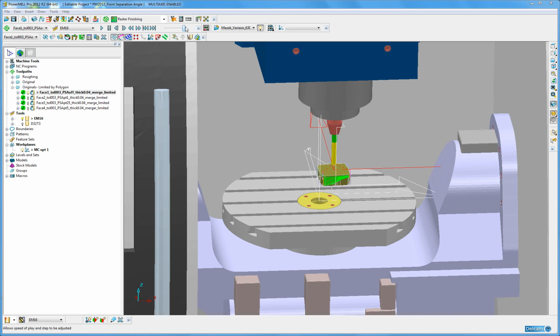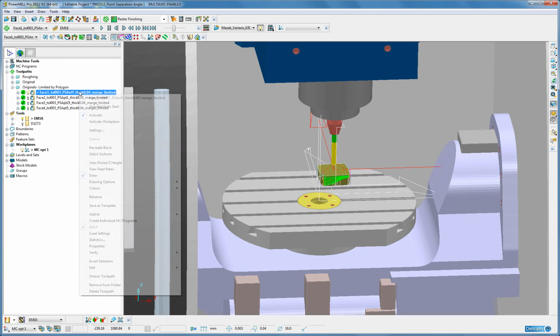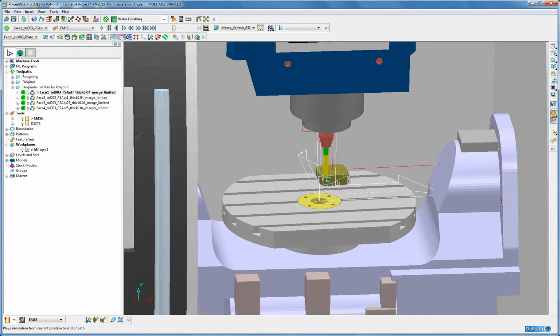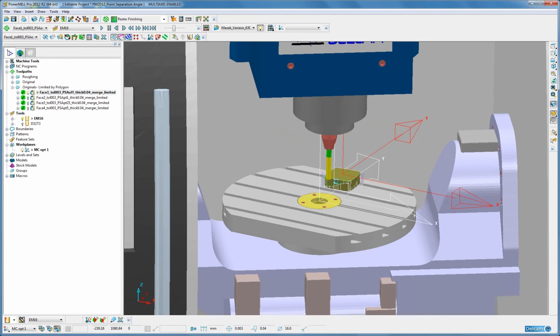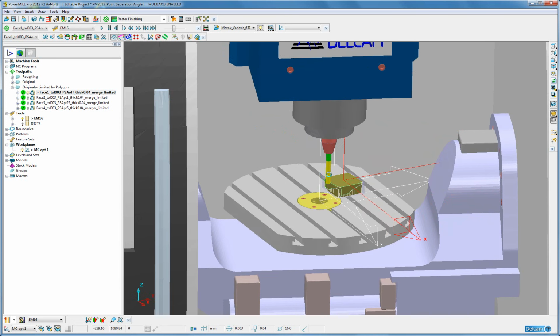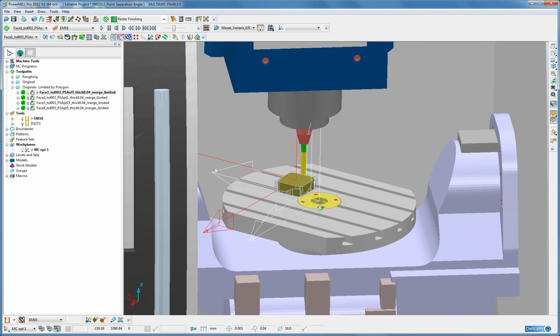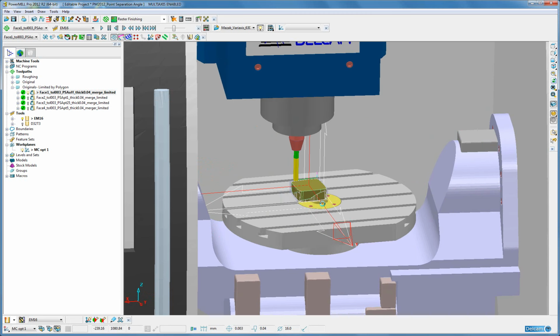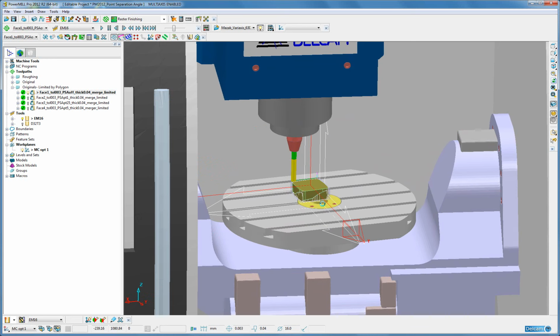This is best seen if we simulate on the machine tool displayed, where the tool is going across the face at a constant level. When it gets near the gimbal lock position, the vertical tool axis, a rapid change occurs in the table, spinning it 180 degrees or slightly more. When it returns back, it'll do exactly the same.